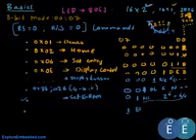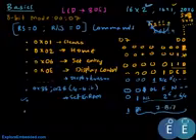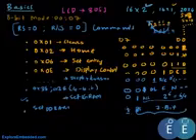Since this one gets here, we have a 7-bit address, and with this we actually display the contents of the DDRAM, or we set the DDRAM address. Now let me just spend a little time here. What this does is, if this bit is 1 and we send a 7-bit address, it actually corresponds to an ASCII value in the CG-ROM.